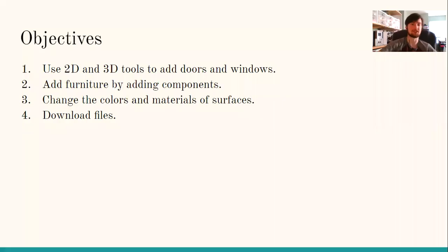Let's have a look at the objectives. We're going to add doors and windows using 2D and 3D tools. We'll add furniture by adding components. We'll change the colors and materials of surfaces, and I'll also show you how to download files.